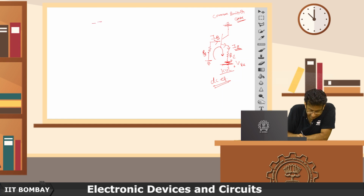If I apply KVL, what I get is IB RB minus VBE minus IE RE plus VEE equal to 0.